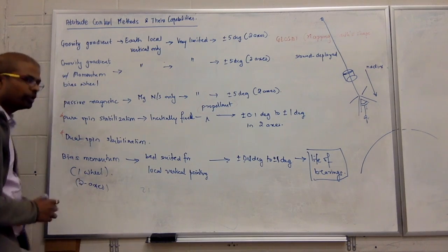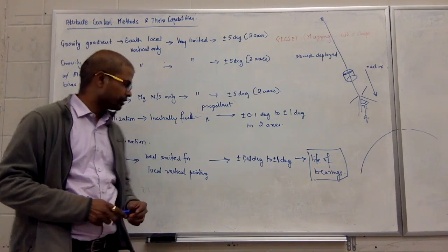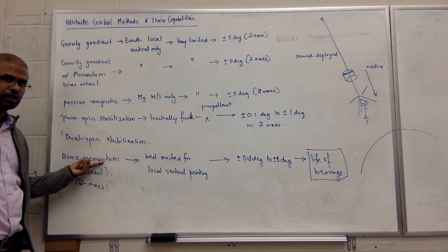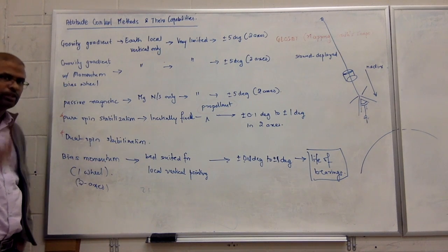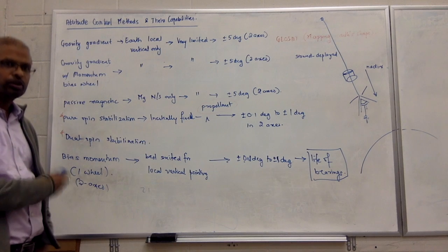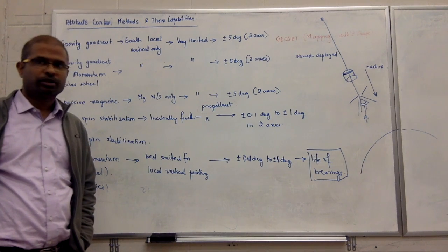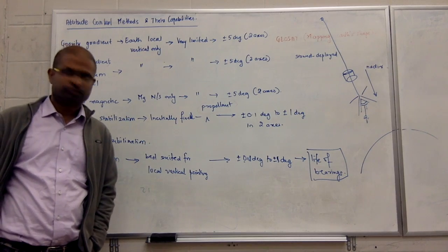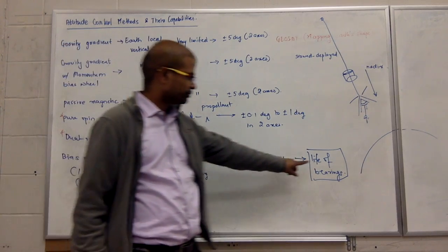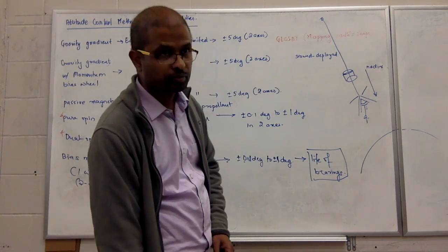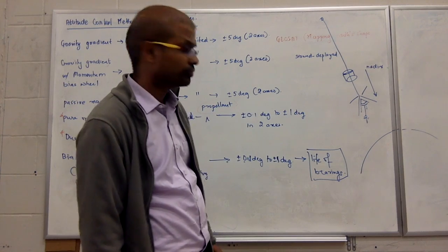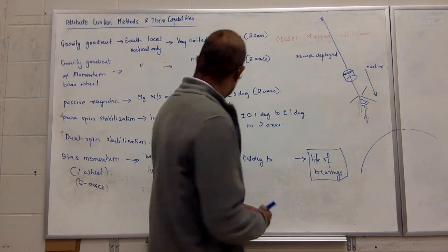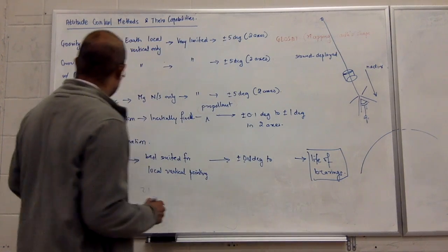There can be really only one wheel. If it's a momentum bias spin stabilized satellite, there is one wheel. Many satellites were launched like this. The life of bearings is a concern. Is it the dual spin stabilization? There are 2 different kinds of bearings. Yes, these are 2 different things.